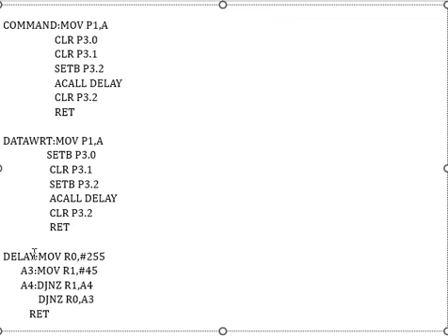Finally, that is nothing but the delay subroutine. Generally, it is better to keep a delay of 20 milliseconds. Once you keep that particular delay, that is sufficient.